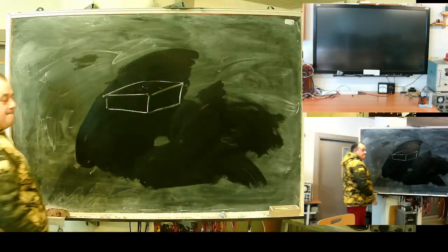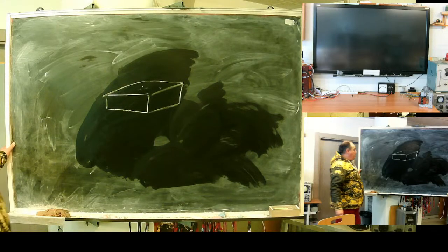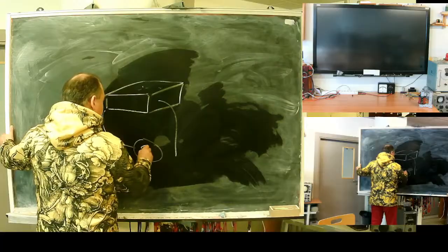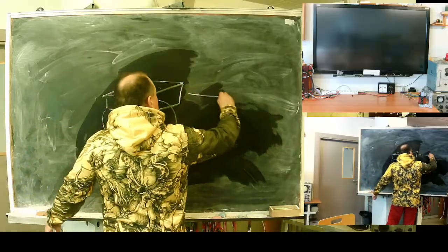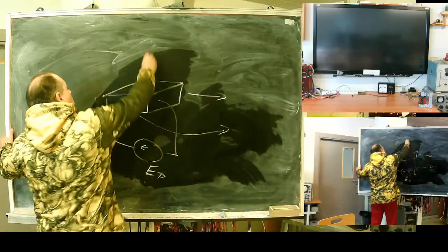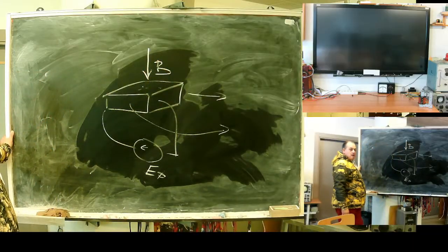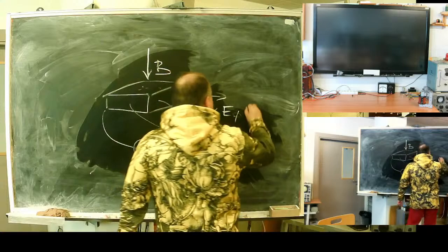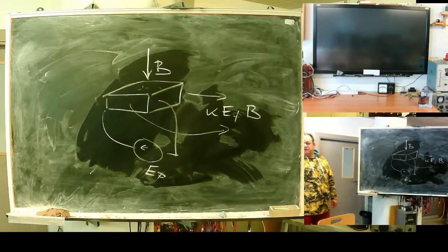If you take, say, a block of, for example, germanium, apply E0 on one side, here will be your output, and put it in a magnetic field. Without the field the output will be zero. With the field, output will be proportional to the magnetic field.